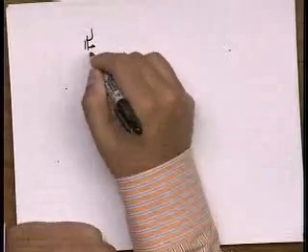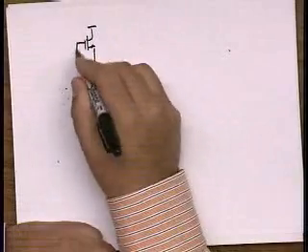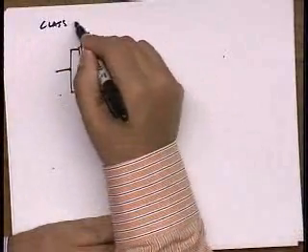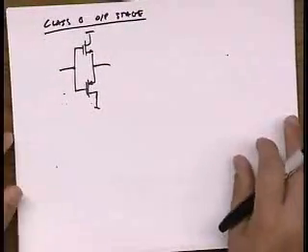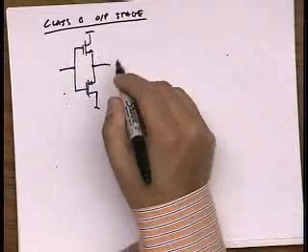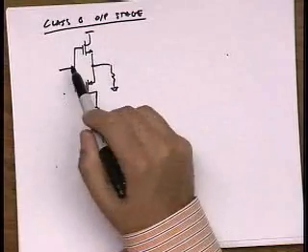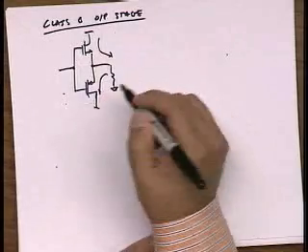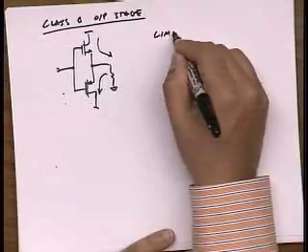So if we do the same thing with CMOS devices, let's say this is kind of the class B output stage that we might use. And again, it's the exact same circuit. It's a follower driving a resistive load, low voltage gain, high speed. For positive input, this device delivers current. For negative input, this device sinks current. And I think everybody knows the problem with this device is limited swing.